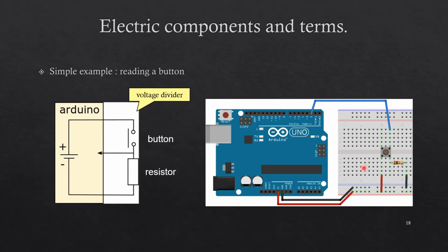And of course you need to connect that button with a resistor. The resistor that we use with the button is a 10k ohm, and the resistor that we use with an LED is 470 ohm. You can connect the resistor in this way, and you can take one of those pins and connect it to the input pin of your Arduino.